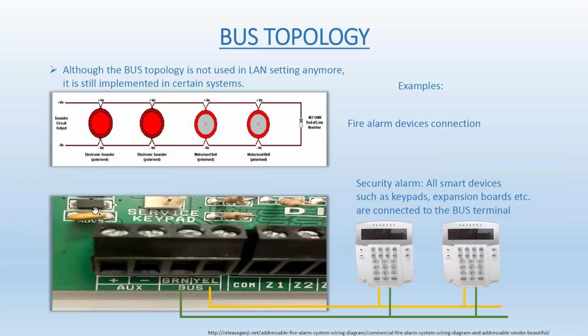All right, so I'm giving you some real life examples. How is the fire alarm connected? Fire alarm sensors are connected to a zone circuit. What is a zone? A zone is a point on the alarm panel that can be triggered. And that point can be annunciated in the annunciator panel, and it could also be named.